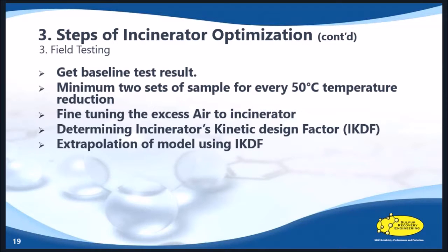The second thing is to take note of safety. Different facilities have different safety standards and procedures. For stack sampling, SRE prefers to collect samples from the middle section of the stack or at the same platform where the analyzer is located.